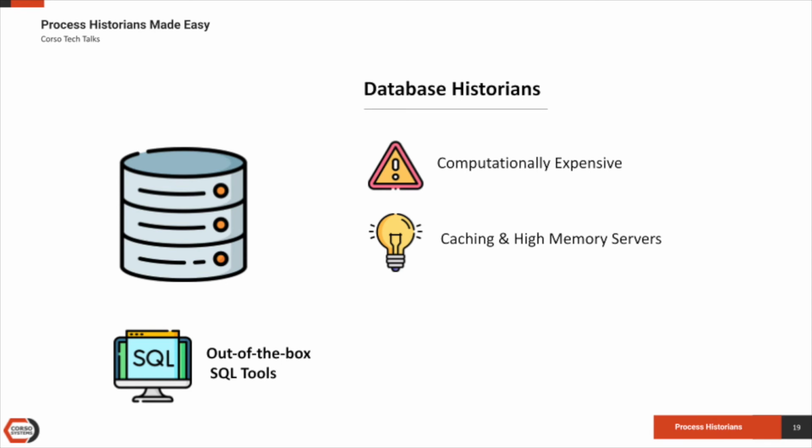There are also some clever tricks like using the tag history splitter with Ignition to break data up into different chunks to speed up retrievability across different tables. If you're querying a year of data out of a single large table containing multiple years of data versus querying a month of data out of a smaller table, the month will be queried faster because there's less data to process.